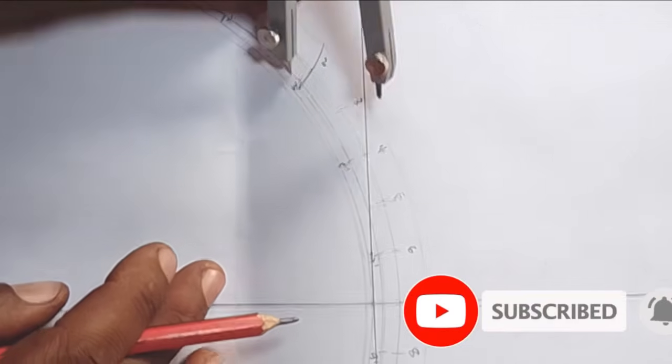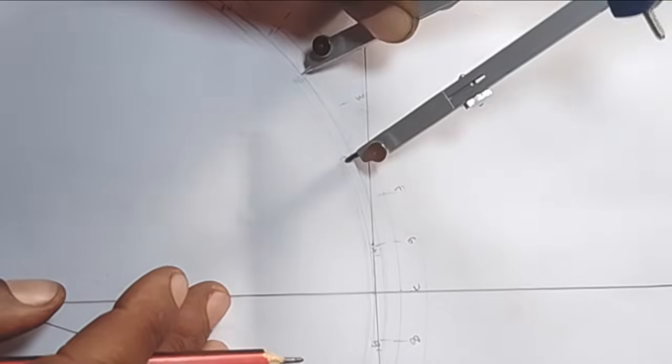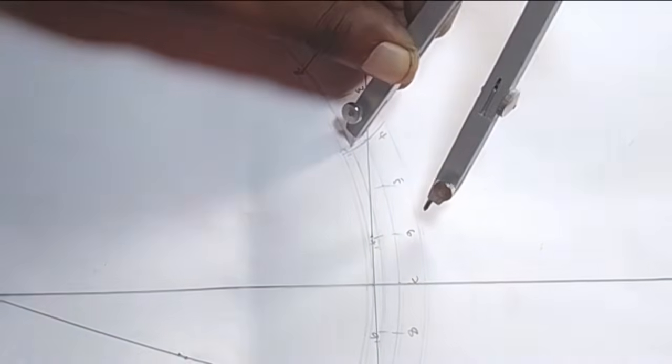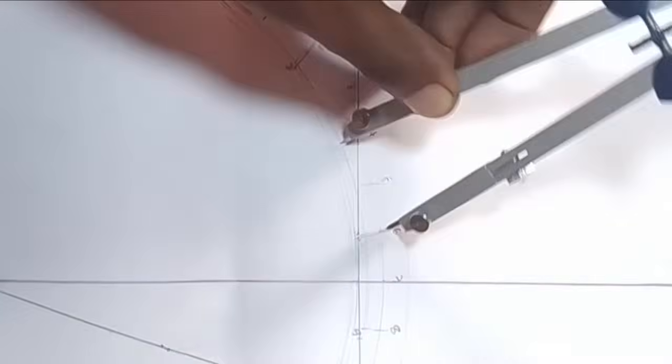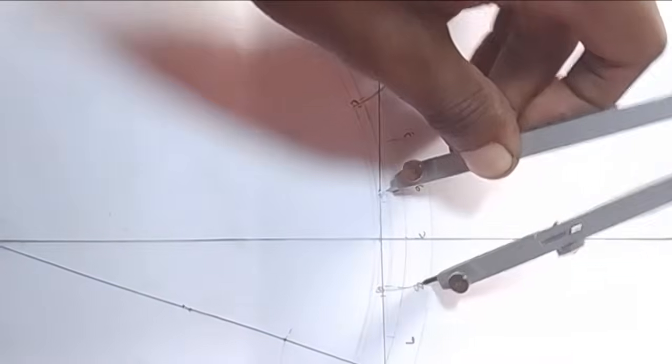Stand on the next point. The next point was 3 prime. Again, strike an arc that does not exceed that baseline. What was our next point? This was our next point, 5 prime. Again, strike an arc that does not exceed that point. Stand on the next point. Again, strike an arc like that.